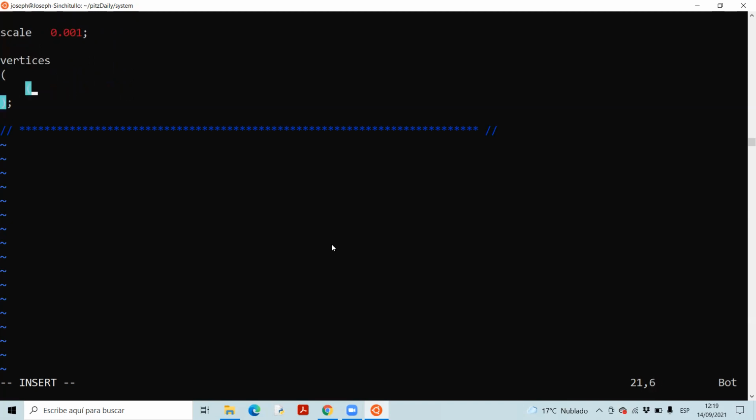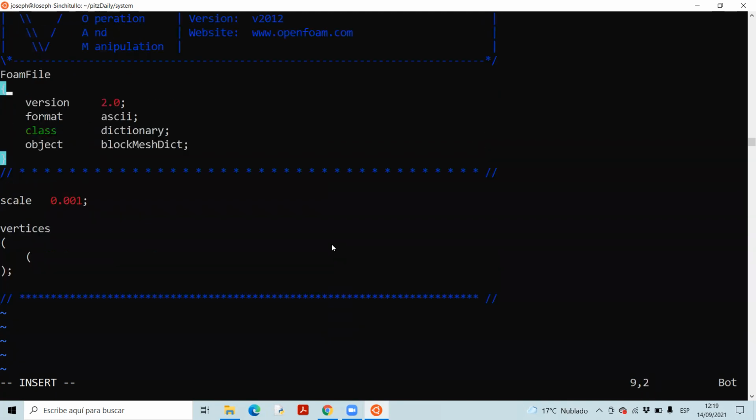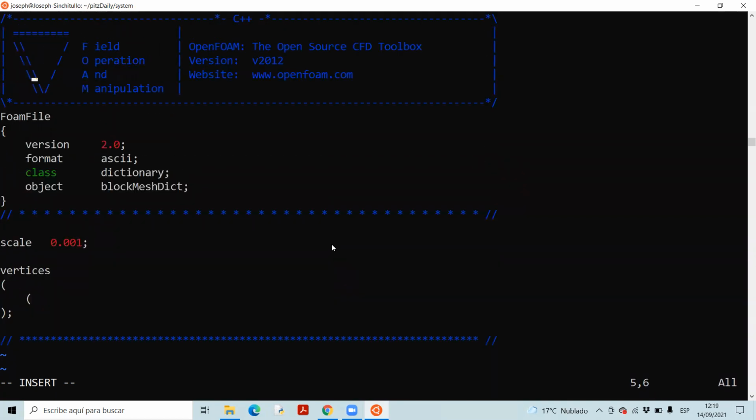Now first of all, we will write from here what our vertices are and how we can create our simple block. I have removed all things from your file. Let me make a simple 2D or 3D block for you. This is how I'm going to write blockMesh in front of you. The first point will be 0 along the x-axis, this 0 is along the y-axis, and this 0 is along the z-axis, and I have closed it.